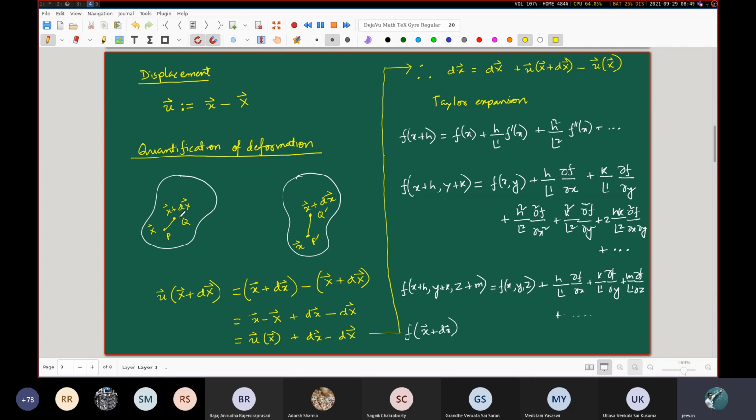So you should not think of anything which is lying along a surface for the shearing direction. Rather, you go back to the geometrical interpretation of the shear which you had studied earlier. So what is the geometrical interpretation of the shear strain? So we consider a small point mass, and for that, the angle between the two perpendicular lines, how much it is changed. Yes, that is the important thing.